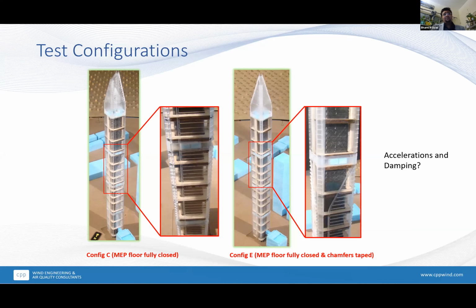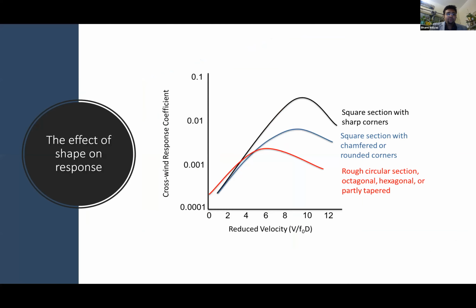Now, with really high accelerations, if it's an office space, there are different criteria where it's acceptable compared to a residential space. In really slender buildings, particularly in the downtown areas of various cities, damping systems may have to be involved. There are different kinds of dampers, whether a simple TMD or an FVD, fluid viscous damper, and so on, that have to be employed in order to control the wind resistance.